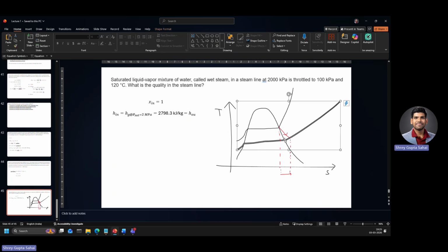One important thing here, now that we know that the pressure drops and entropy increases, we are for sure in the superheated regime. That is the important thing. We cannot go down unless it is told to us that there is some heat exchange happening, that this is a non-adiabatic process. But because there is nothing given here, if you try to assume that there will be some heat transfer and it's non-zero, then you will fall into the problem of more unknowns than knowns.